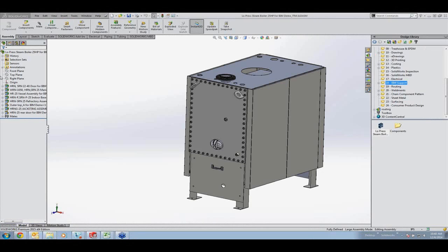I'm not sure what's going on there. Anyways, what it did was hide all the fasteners here, and it removed some of the holes. So the hole here in the AEC software was not shown. Then I click on Save as SAT file, type in my name here, and hit Save. And then this is ready to export into the architectural software. Apologies about that preview. I didn't do anything different.